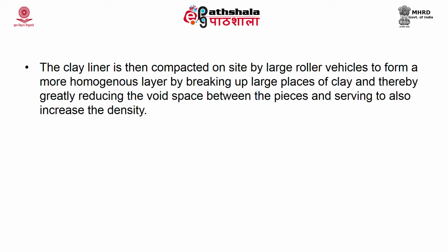Once it is spread on the landfill site using a bulldozer or a scraper, you have to compact the clay. The clay liner is then compacted by large roller vehicles which move over it, and it will homogenize the layer. Even if there are some large particles of clay, they will be broken and you will get a homogeneous mixture of the clay liner.